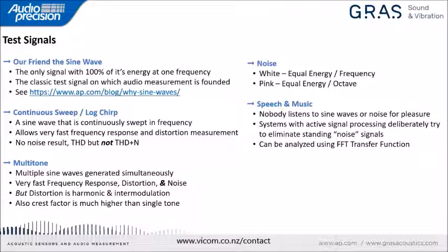Now, particularly for acoustic measurements, say measurements in a room, perhaps tuning the speakers installed in your living room, it's actually quite common to use noise, just random noise. And we have two varieties that we'll most commonly see in the audio measurement world, and that's white noise. White noise has a flat spectrum in an FFT analyzer, and it has equal energy per frequency.